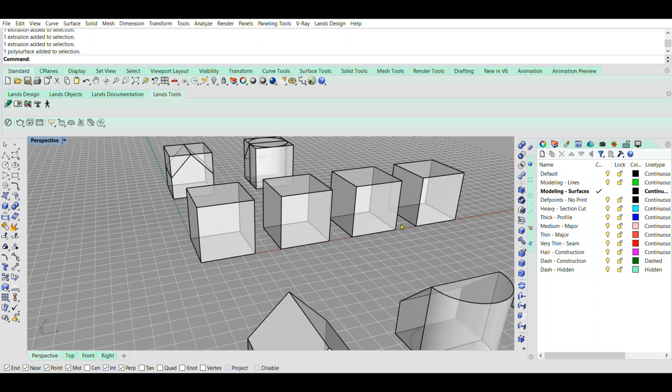To do that, we will utilize 3D shapes and/or extrude 2D geometric profiles and planar surfaces that can be used to split, trim, Boolean difference, and/or Boolean split commands to edit and manipulate the original cubes. So split, trim, Boolean difference, and Boolean split, those are all commands that you type in. Those are all commands Rhino can use to manipulate this geometry. That will edit how these cubes will look.